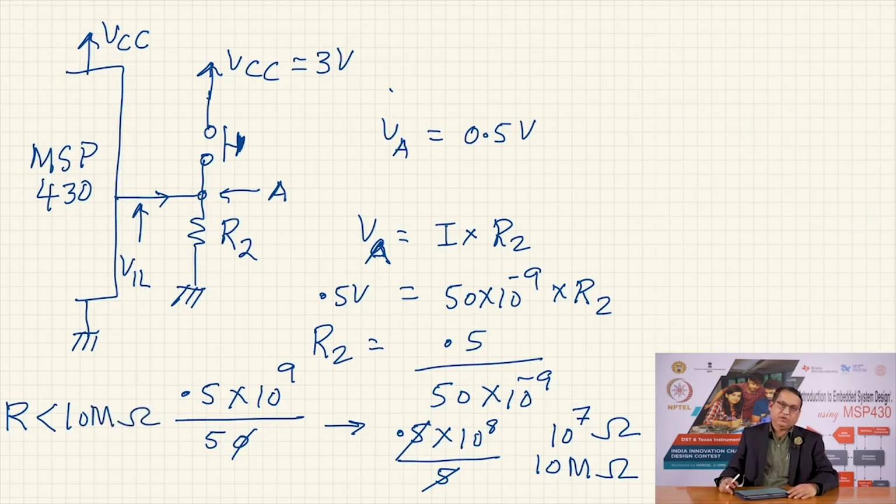So, I could again use a 1 mega ohm or 470 kilo ohm resistor, just because I am going to use that value for the pull up resistor. So, I could use an identical value, it would lead to a voltage drop which is much smaller, lesser than 0.5 volts, and therefore, I would have translated the two states of the inputs, that is on and off state of the input switch, into logic 0 and logic 1 well above the high threshold or low threshold as the case may be. And so, this is the way to calculate.